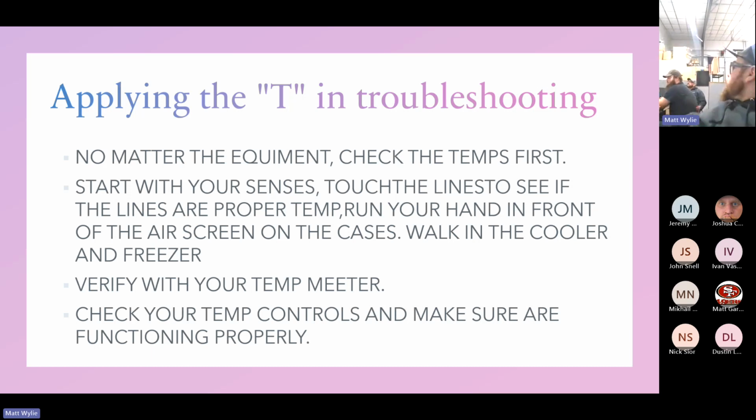Especially what the customer goes off of for walk-in boxes, right at the door. They have those thermostats on the side when you open the door. Those are always way off, and that's what they check the temp with. Oh, it's reading 45, because they just got in stocking, or their hinges are bad and the door closure's bad, so it won't shut.